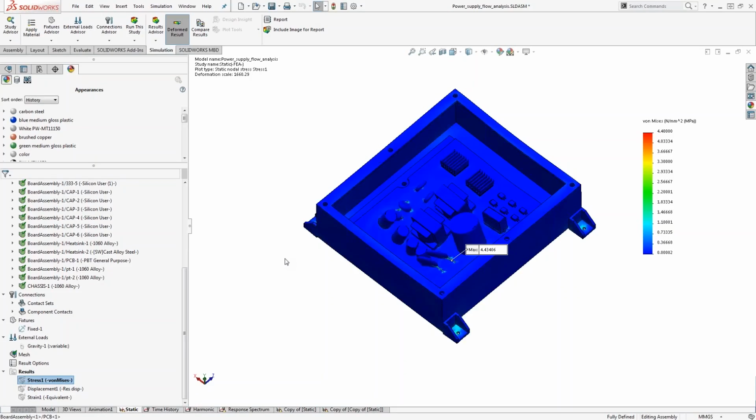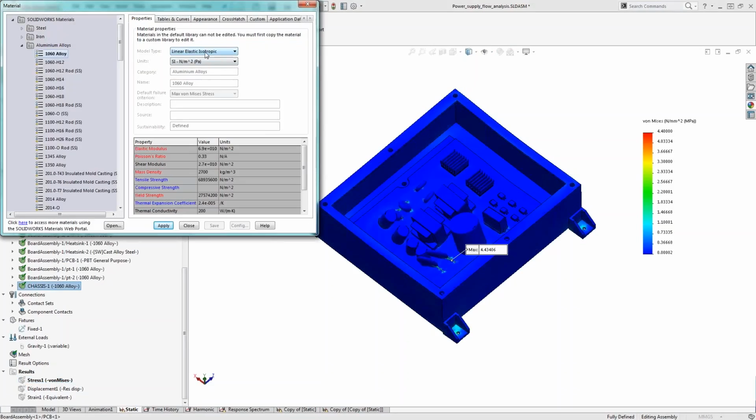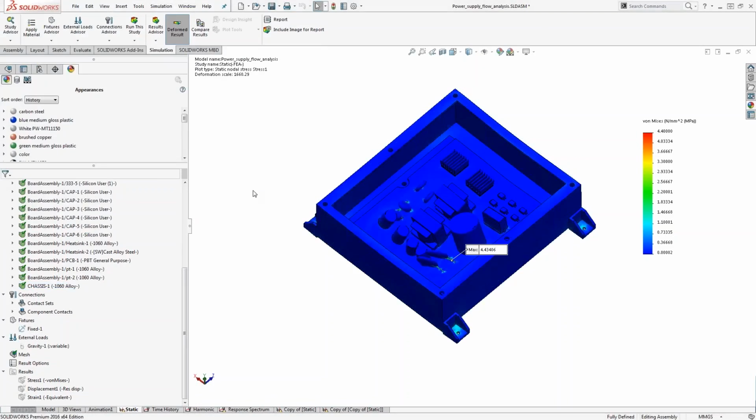It's probably overstressing it, and we may need to consider some sort of nonlinear problem to account for any plastic deformation that it might be experiencing. The reason being is that a linear static analysis assumes that there won't be any large displacements, any large deformation, no permanent deformation. It's only going to assume that all the components behave linear elastically. So if I take a look at my material here, you see that the only material type I have is linear elastic. If we imagine a stress-strain curve, it's only going to behave linear elastically.